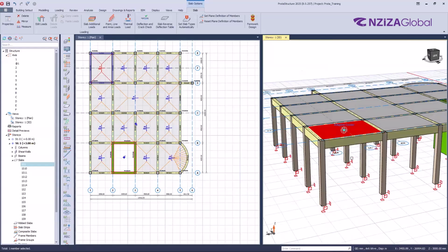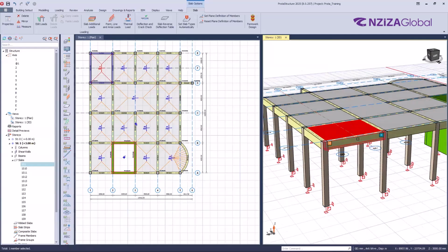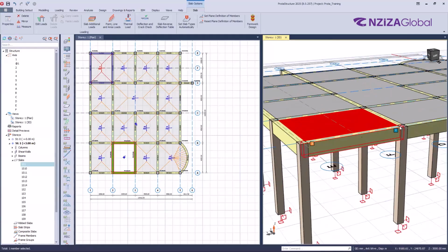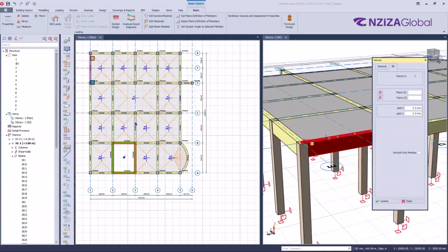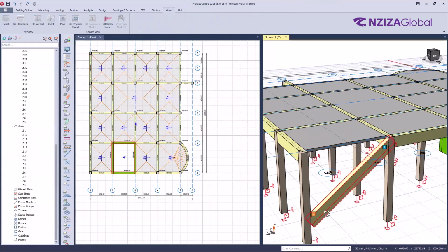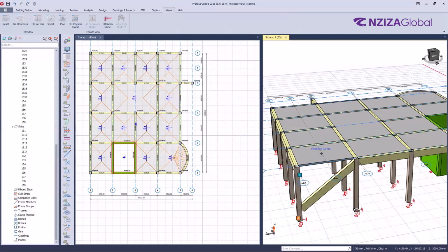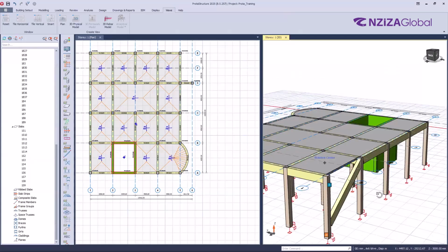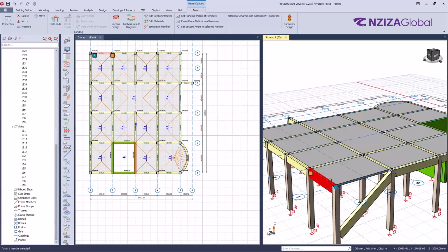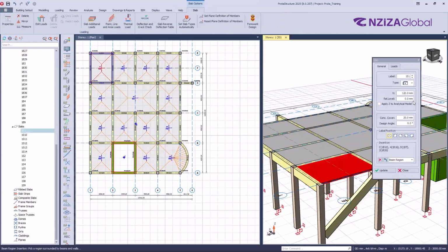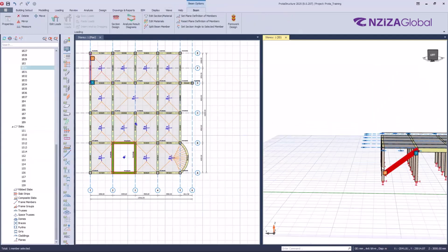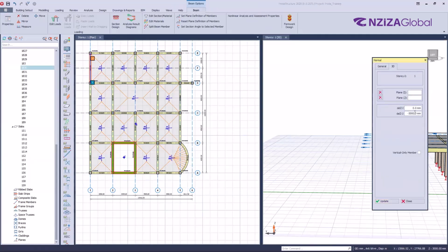So if I decide to use the delta Z, I will be able to incline this beam. You remember, you can use this. This is the J end. If I put negative and click on update, it will be inclined. It's okay for the beam. It can be inclined. I can even lower down this one. But how about the slab? Because the slab, if I open the property, I don't have those delta Z to change the position. So to achieve this, okay, let me bring this back to its normal position.